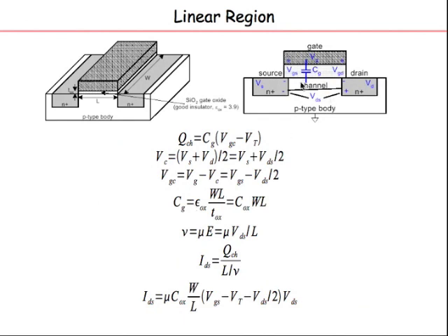So what is the charge out here? Charge on that capacitance is Cg times the gate to channel voltage minus Vt. Remember that the channel forms only after the gate voltage exceeds the threshold voltage. So that is why we have to pay a kind of toll tax. Vt is gone, so you have what is called overdrive, not overhead, overdrive, Vg minus Vt. Okay, Cg times Vg minus Vt, which is the charge in the capacitor.